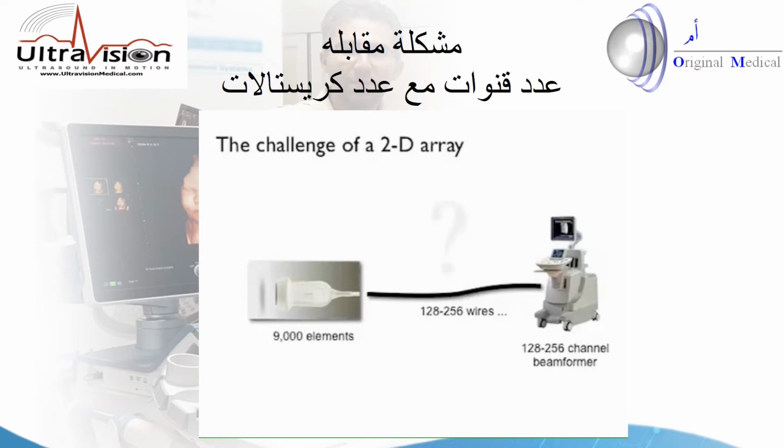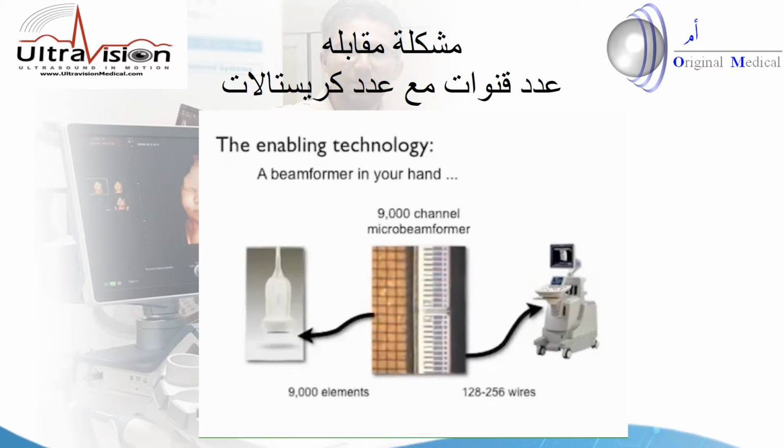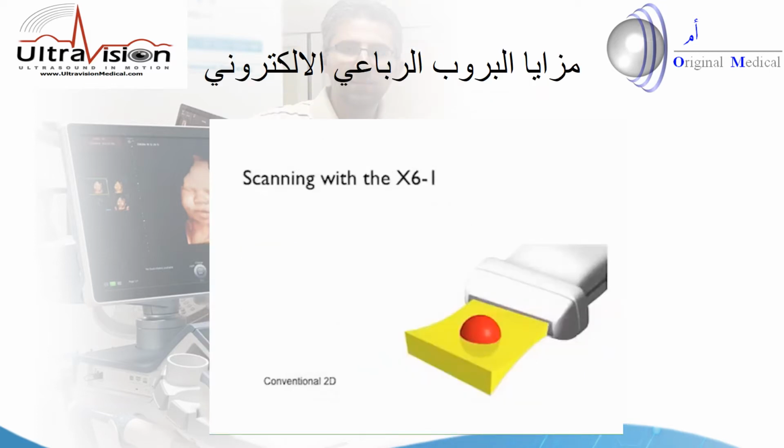And really the enabling technology that has allowed this development to take place is that of the beamformer, the 9,000 channel beamformer, which is not in the ultrasound system but in the probe itself. So those 9,000 elements are connected to integrated circuits which then form the beam and send through a similar wire to the ultrasound system sets of data which correspond to the commands given to it by the host system. So when you scan with an X61, you're literally holding a 9,000 channel beamformer in your hand.